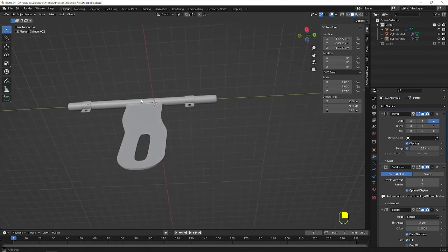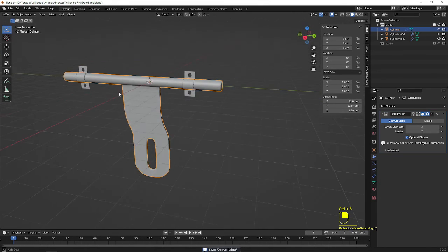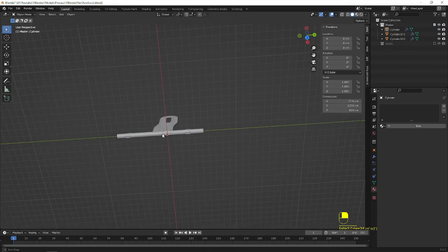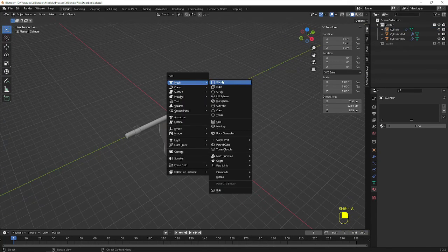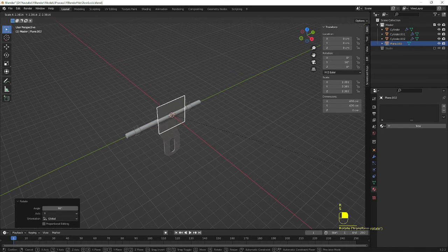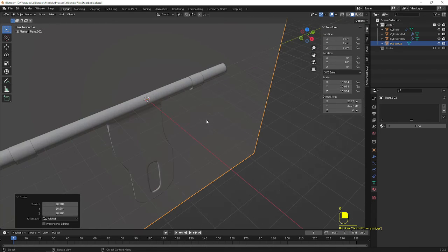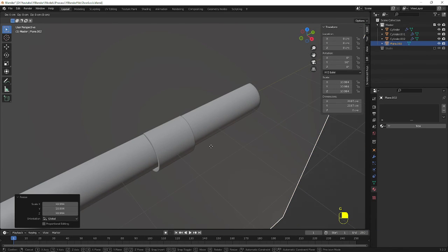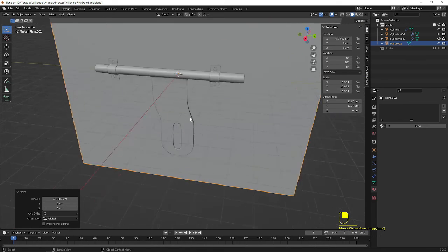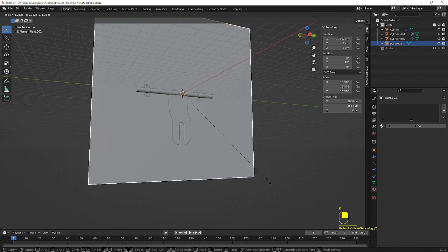So let's go to applying the material for the same. Go to the material tool, and before that we can add one plane sheet for the appearance. Press Shift A and create a plane, rotate it in the Y axis 90 degrees and scale it up, then zoom in and move towards the X axis to make it visible like this. So I make it a little bit bigger.